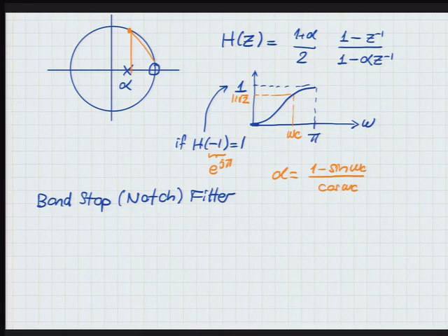Notch means you want to go straight close to 1. You want to dive in to stop a certain range of frequencies, and then go out again and level around 1. You can't do that with one pole, one zero. It's just, you can't. So the lowest order filter you can accomplish this with is a second order filter. You'll need two poles, right?